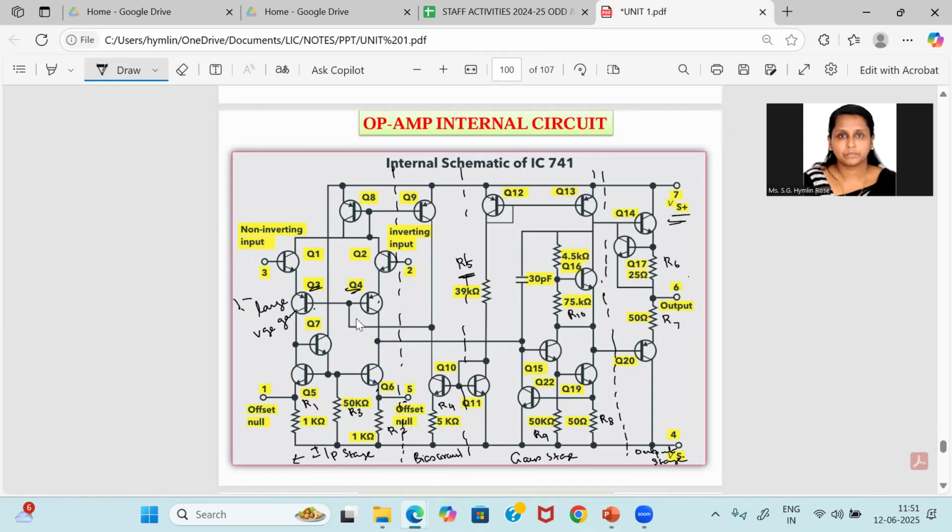So this is about your input stage. The input stage is followed along with the biasing circuit. It runs from Q1 to Q8, and from Q8 to Q12 follows the biasing circuit. Q1 and Q2 form the emitter followers, whose output currents are inputs to the common base amplifier using Q3 and Q4. Because of Q1 and Q2, you have high differential input resistance, and because of Q3 and Q4, we can achieve large voltage gain. Also, they provide additional protection against voltage breakdown conditions. As they are PNP transistors, we can have an emitter base breakdown voltage of about 50 volt, which is very high.